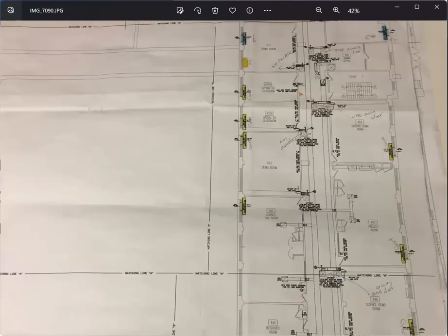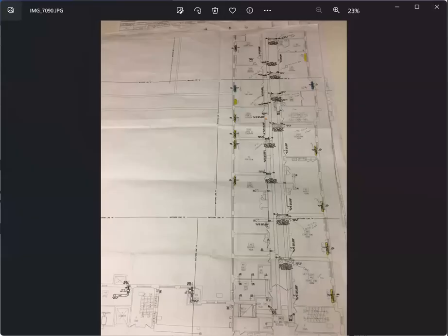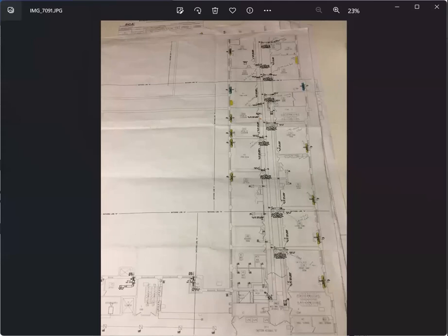That's a different drawing. This is a construction drawing. The shop drawing is more accurate, but it should also be approved and reviewed by the design engineer or the engineer of record.